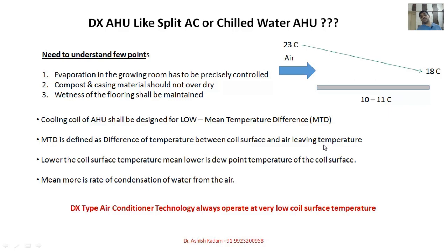So if you have, suppose, 1 ton of refrigeration load, it will consume 0.8 kilowatt of electricity. Means for every 1 hour you will have 0.8 kilowatt hour of power consumption. 0.8 kilowatt means you will have 0.8 units of power.